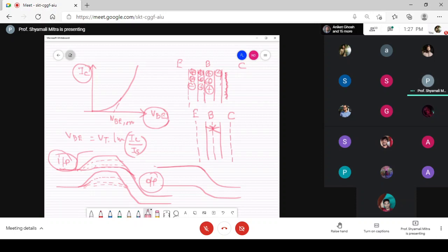That is called punch through. This phenomenon is known as punch through when the base is very, very thin. But what if we want to make the base thin without the depletion? Now I have understood the problem that the base should not be made so very thin that these two depletion regions will merge with each other. Now, if we are able to make a base thin without the depletion regions hitting each other, then what another thing can we actually do to make the emitter current go past towards the collector current to gain the maximum efficiency.